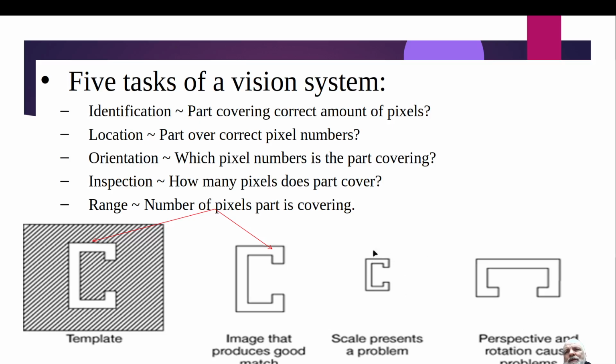With a 3D camera, using multiple views, we can detect maybe how far away that is. But if we're using just a standard 2D camera, we can't detect if the part is further away, or it just looks smaller than what we were trained. So this is what we were trained. We trained the robot to identify this, and even though this is the exact same shape, it's not the same size, so the robot doesn't think it's the same part.